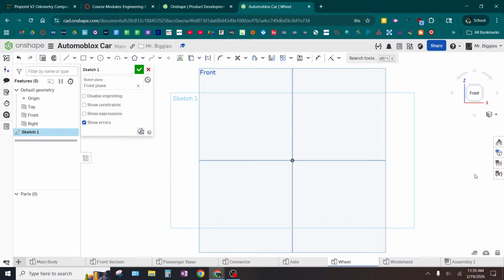Okay. And the first thing that I'm going to do is draw a random vertical line at the origin. The height is irrelevant. All that matters is that it starts at the origin, just so it's grounded in the coordinate system, and that it goes vertical. So you should use that snap to vertical constraint. The reason why the height is irrelevant is this is going to be a...